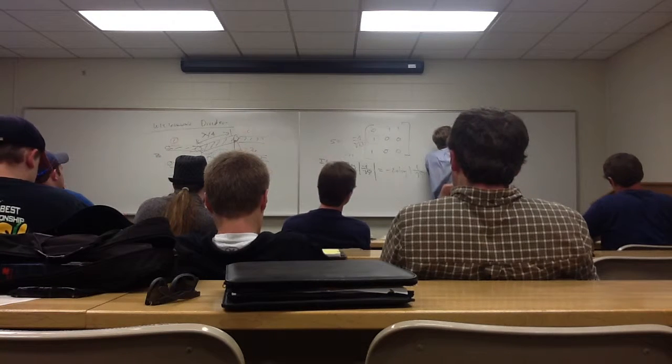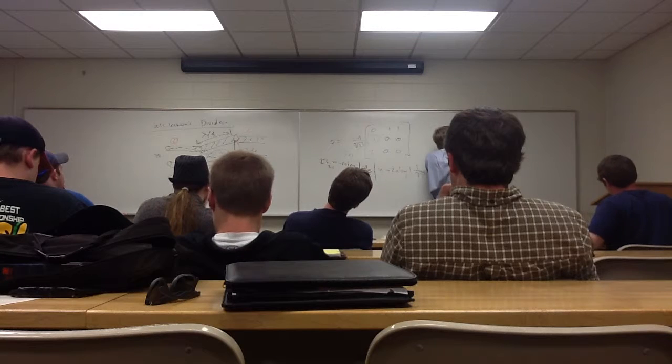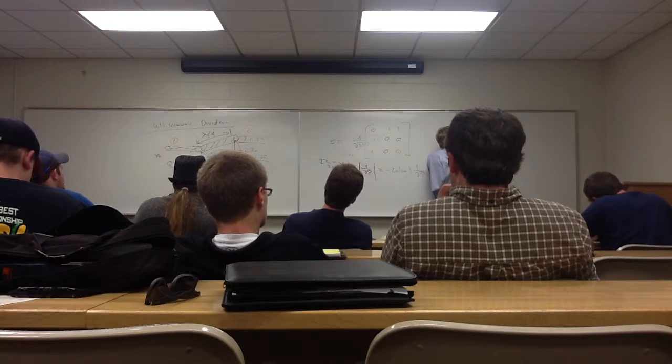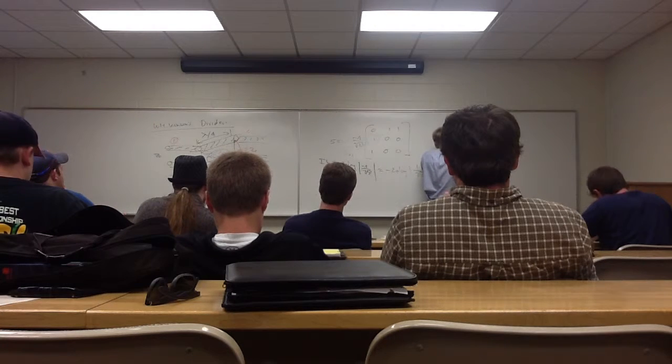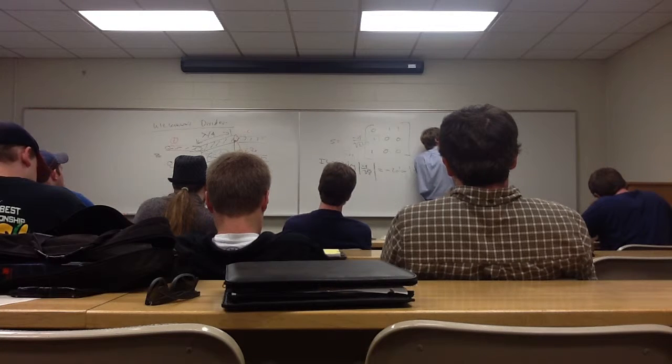First of all, this length would be lambda over 4. This characteristic impedance would be square root of 2 Z naught. And you have another line down here. This characteristic impedance here would be square root of 2 times Z naught. This length would be equal to lambda over 4.